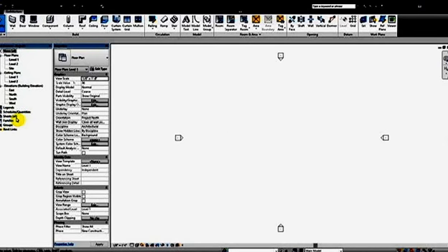Next is sheets. Sheets in Revit are the graphic representation of what you would actually be printing. So this is where you would lay out your views, your title blocks, your images, your notes, all that onto a sheet. That's where you compose your sheets for printing. And again, you can sort the sheets by various different categories as well, like you would with the views.